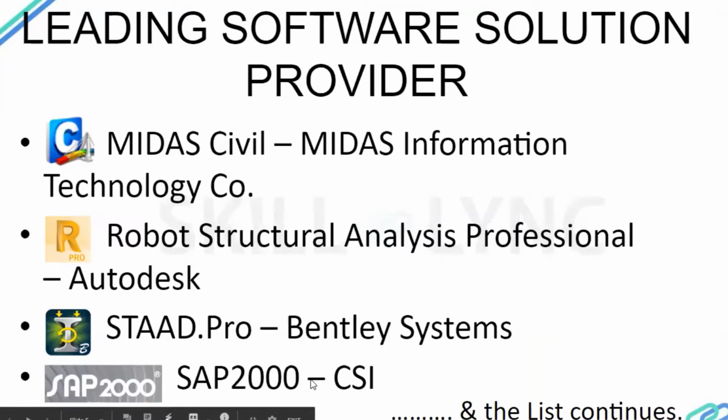Typically, the software that we are using in our design offices these days for elevated metro viaducts is MIDAS Civil. It is a very widely used software, and it has the ability to do time-dependent modeling of the structure. For example, some of you might be familiar with Staad, which is also one of the software that we use extensively. But in Staad, the issue is that we cannot do a time-dependent model. For example, we cannot model a structure from day 0 to 100 years of its lifetime.